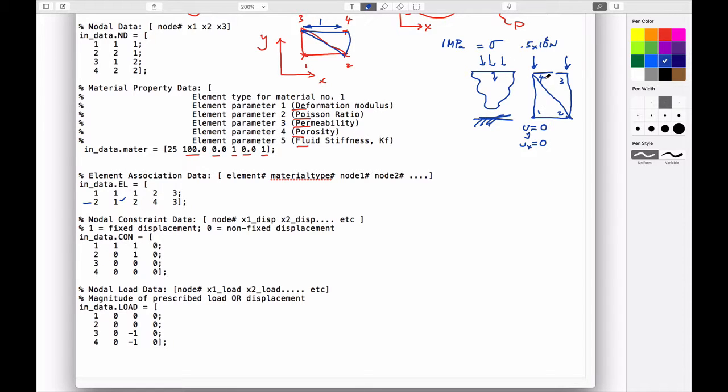And this would be a fluid pressure. So in other words, we'd want the fluid pressure here to be held equal to 0, which would be a drainage condition on this boundary. And the magnitude, depending on how we do it here, would also maybe be undefined. So in other words, a better solution would be that Qx is equal to 0.